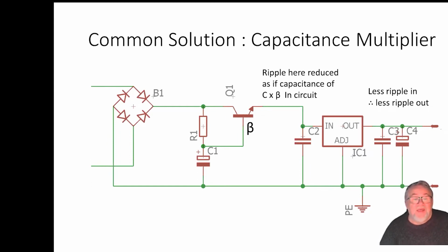It's a circuit that you don't often see. It costs you one transistor and a resistor. But if you've got something that keeps blowing your power supply, think about that. It's a cheap and easy fix.